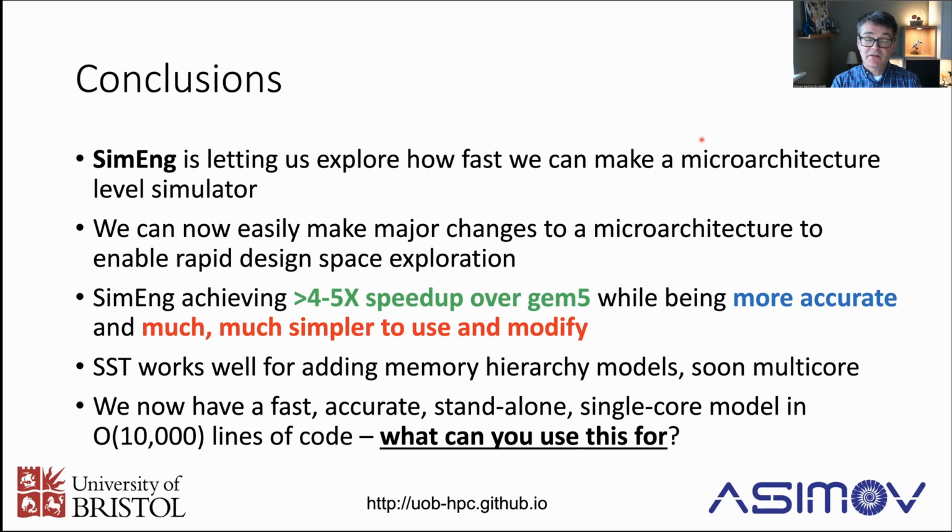And actually what you end up doing sometimes for some models is something would end up going into the code rather than into a YAML file. So you would end up with a model specific version of, let's say, the file that deals with reservation stations. Another example might be which execution units can bypass or operand forward to others, and we've got some generic versions of that.